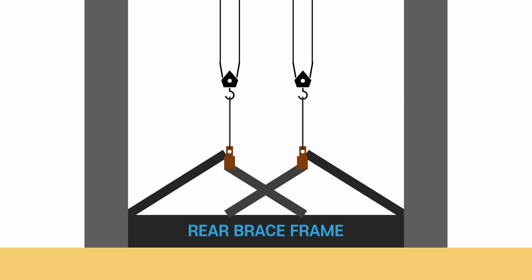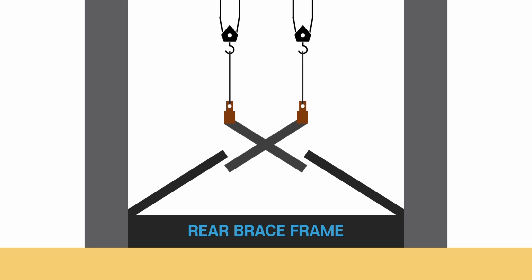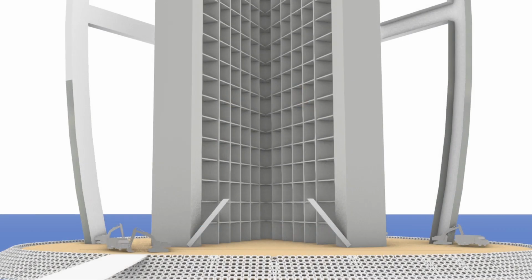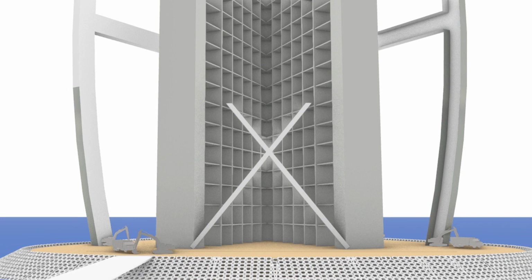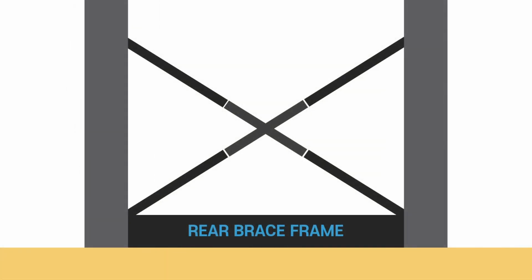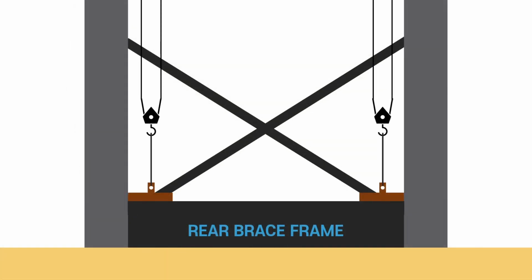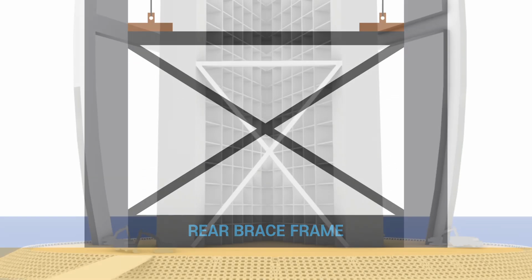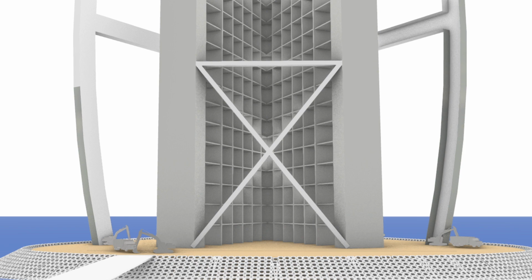Once these two 24-meter braces were erected, then the X of 12-meter length of 52 tons was erected by two tower cranes as tandem lift. The last piece was lifted the same way. By lifting the horizontal frame, one X-span was done. This process was repeated 3 times to create total 3 X's in the building.